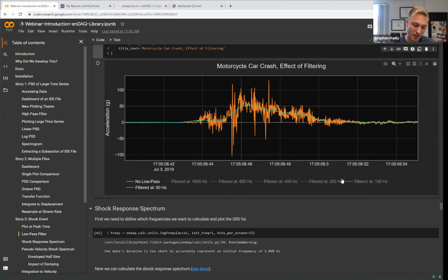And one thing I do want to call out, and I always cringe, is when I see people with acceleration data and they look at the peak acceleration value, which is borderline useless and misleading. I really don't want people to look at peak acceleration.